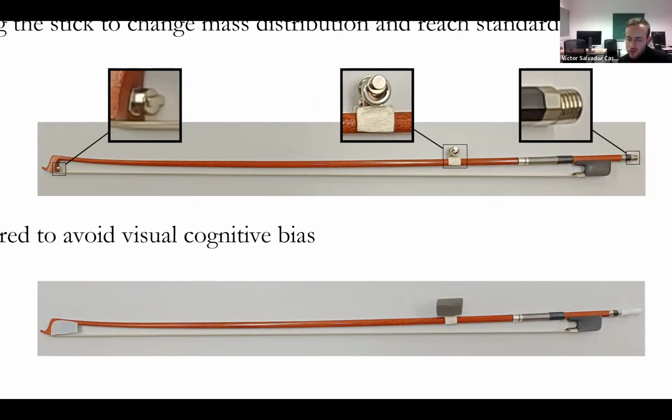So I think that you're wondering about higher moments of mass. In mechanics, there are the moments of mass: the total mass, the zero moment, then the center of mass position, the first moment of mass. Then the second moment of mass will be the moment of inertia. And there is no clear correlation on how higher moments of mass, for example, the mass times the distance cubed,